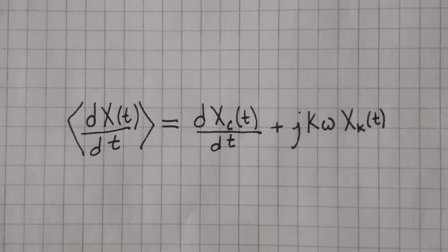Phasor analysis can be added to this with a small modification. If the time step is smaller than the additional signal information, this analysis can calculate multiple time steps of the faster signal before other slower signals create an impact on the remaining system. This is done by using what are called dynamic phasors, phasors which are slower than our fastest signal.